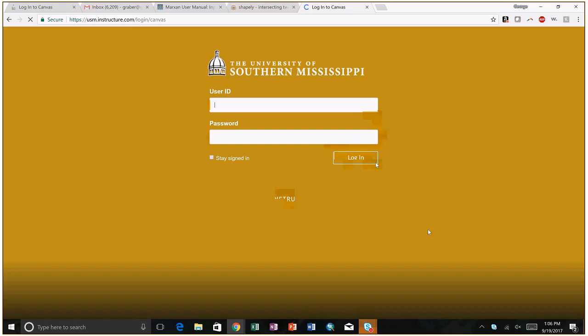like I use it in research to make maps of mangroves in the Caribbean. We don't actually take the drone and fly it using the sticks and fly around the mangrove. I mean, we can, and we do that sometimes for informational purposes, but we want to actually make a map. We just plan a flight line, and the unmanned aerial system uses the GPS to navigate back and forth across the area to collect imagery over that entire area.